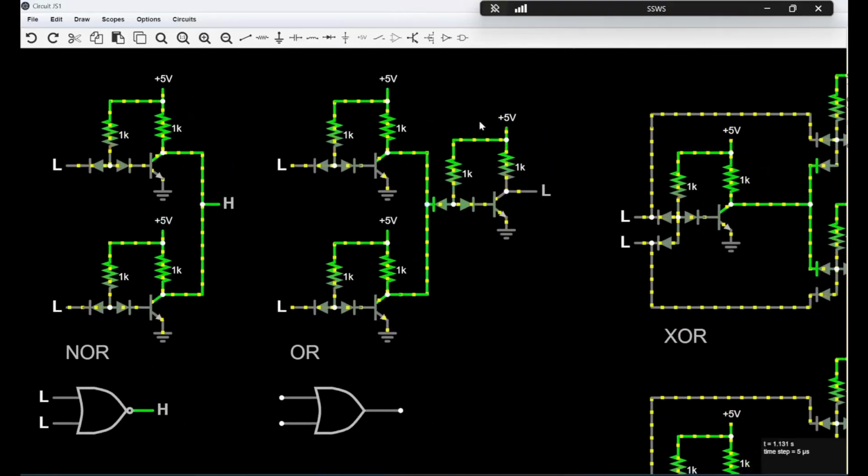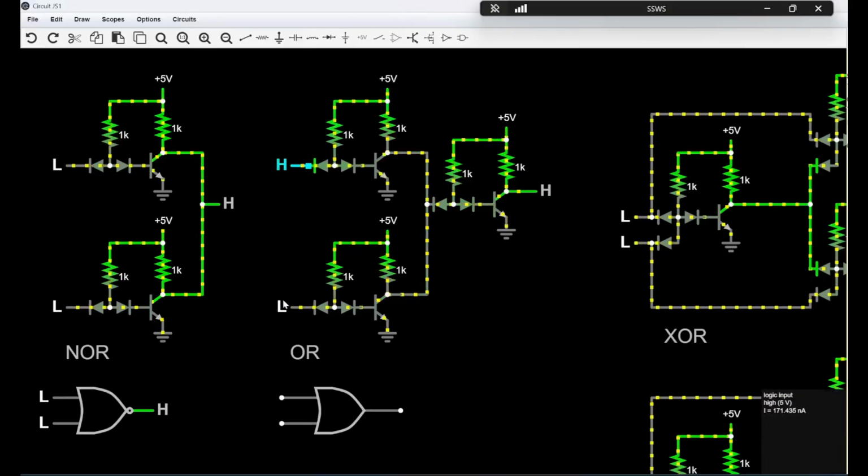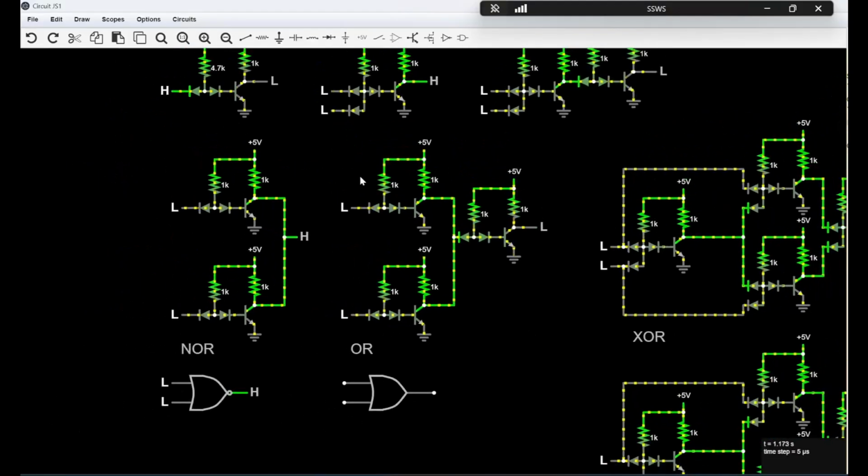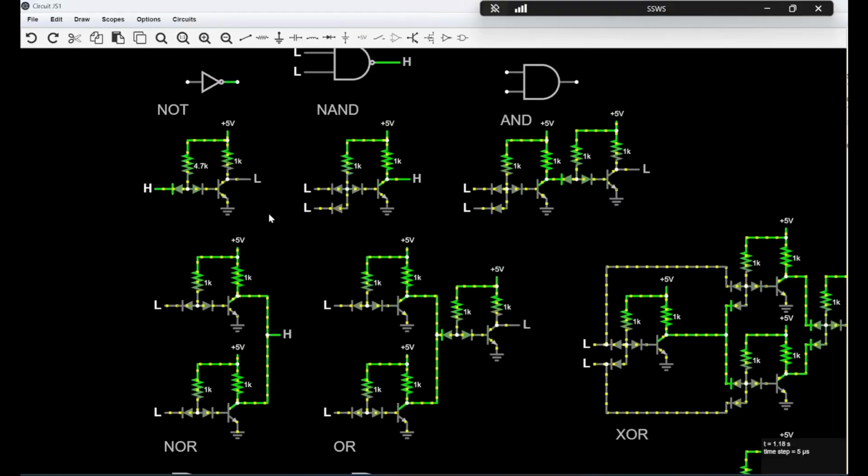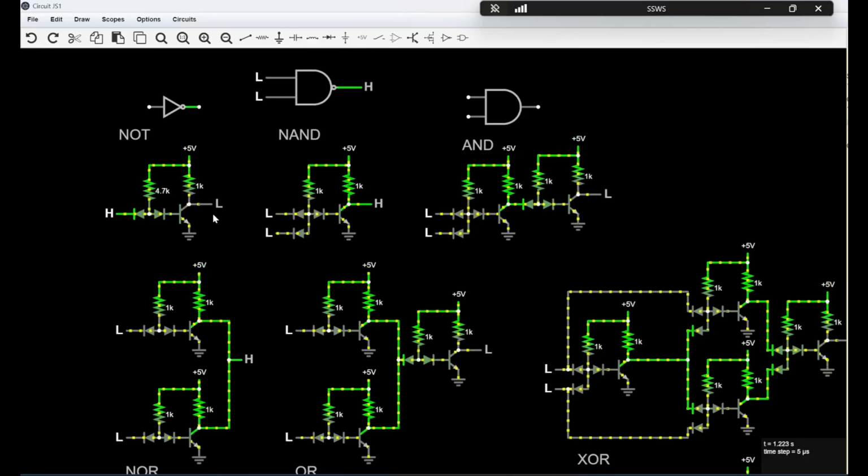And then your OR gate, obviously, is just doing the same thing as with the AND gate. You just invert the output of your NOR gate, so either or both. And there's your 5 basic gates, right? Your primitive gate is your NAND gate. And you can see we're using fewer transistors in the transistor logic, right?